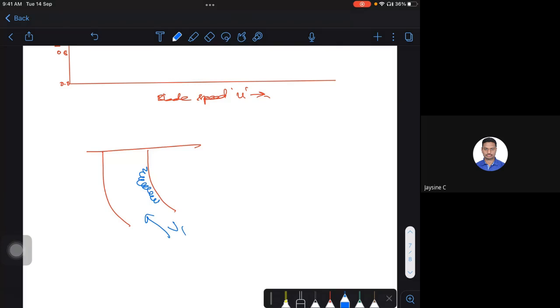So what is the overall thing? This will reduce your V1 by a small quantity, it's a penalty. But what advantage are we going to see? There is less pressure here because I need to create the suction here. Here I have a little bit of high pressure, not very high. There is a little bit of delta P here, and this delta P is very critical in getting the breakaway of the fluid, maybe air or whatever it may be.